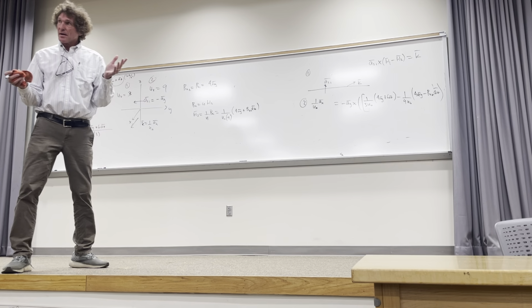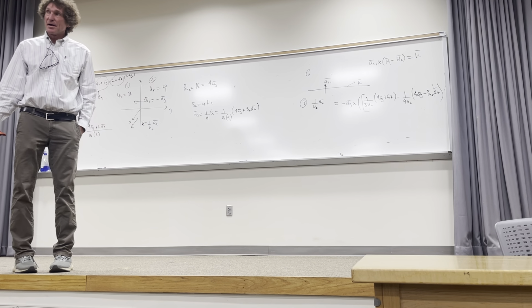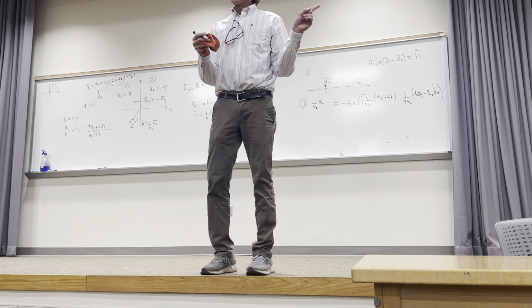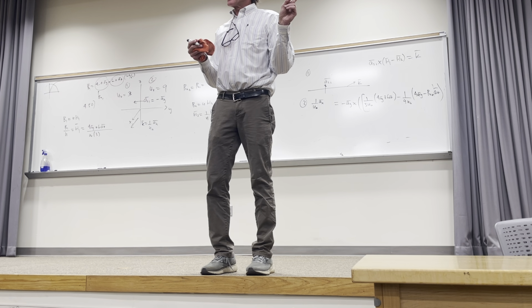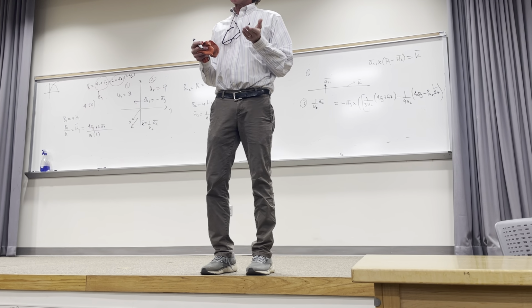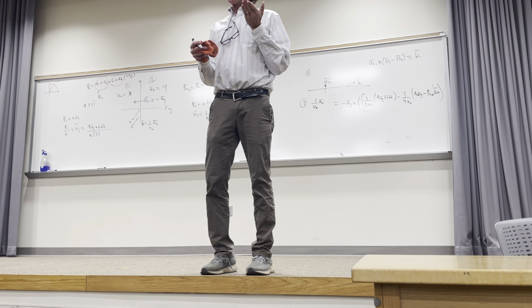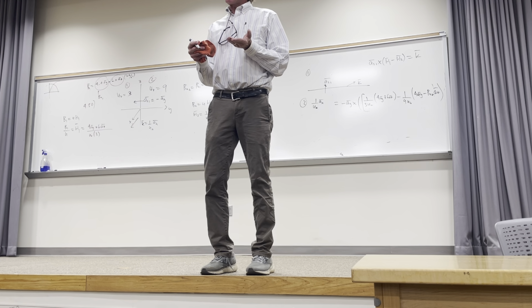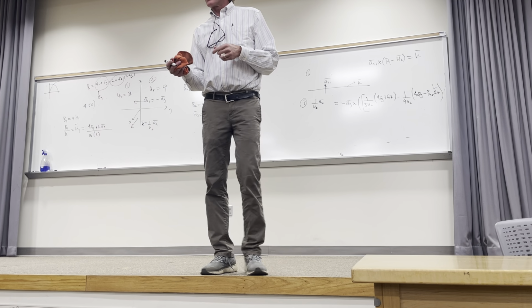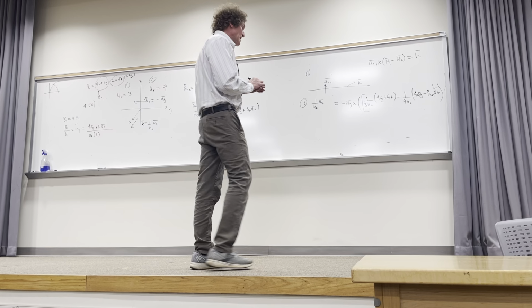Can you say it one more time? Just the equals each other. If this is 0, the normal components of the B field are the same, and the tangent components of the H field are the same. It's very similar to electrostatics, where if you have no surface charge, then E tan 1 is E tan 2, and D normal 1 is D normal 2. Same basic type of problem. It parallels the effects, all right? And that's standard for 99.9% of everything.